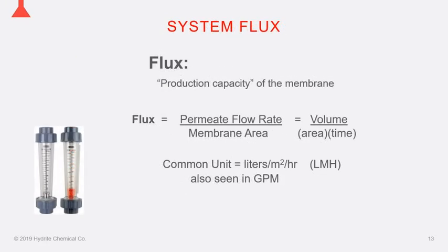That brings us to system flux. Just a couple notes about flux, first of all. Most of us understand that we run a flux test on a system to determine the cleanliness or the state of the membranes, if we brought them back to the state they were before production started that day. So we bring them back to the state they were clean the previous day, and on and on. The term flux is kind of a loose term. Most of us, when we talk about flux, we're actually talking about the permeate rate out of each stage or loop of a membrane system in gallons per minute.